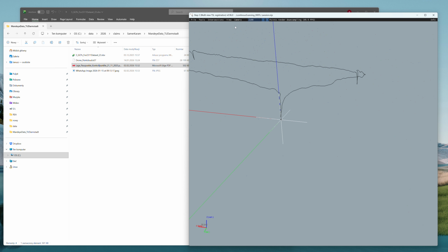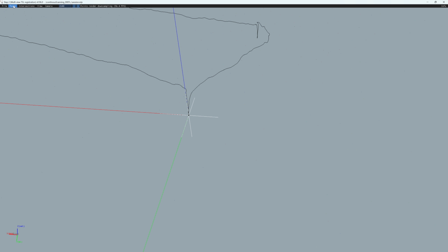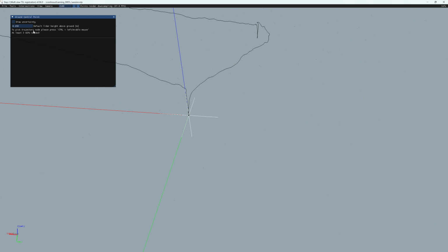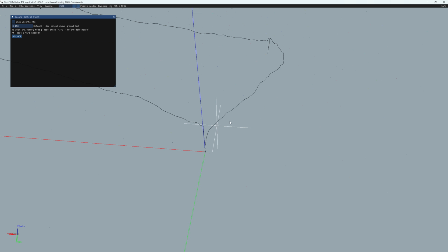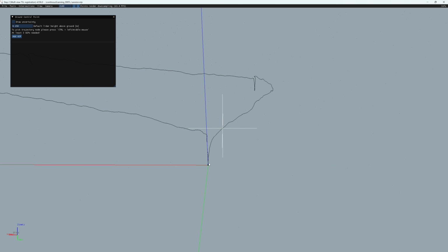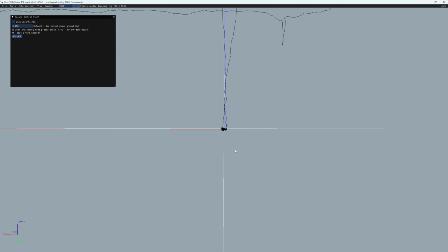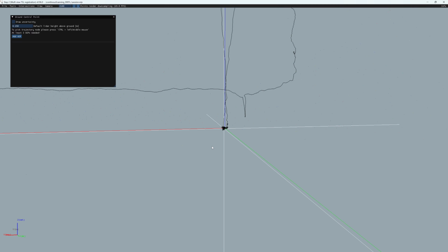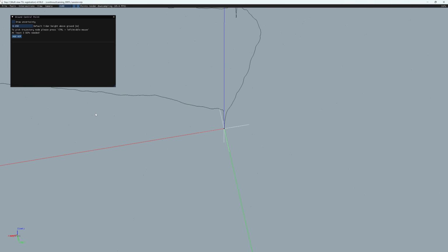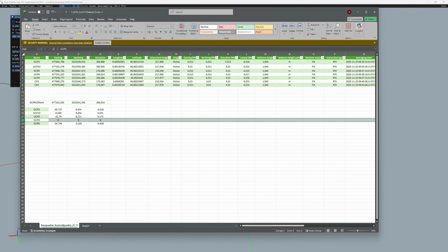To apply a ground control point, first of all, you have to have the ground control points GUI, and it is written: to pick a trajectory node, please press Ctrl plus left or middle mouse. So you can see that I am pressing. You zoom, and you click somewhere in the middle. Okay, it is in the middle, so we can add a control point. We can change the name. The name will be GCP9.